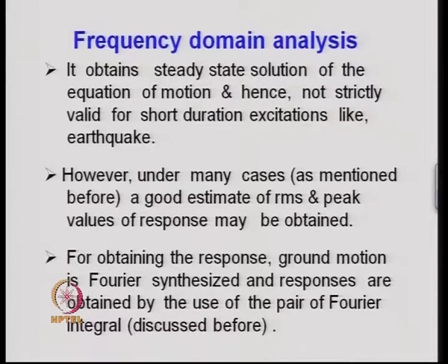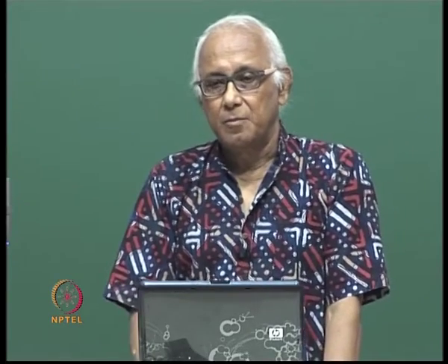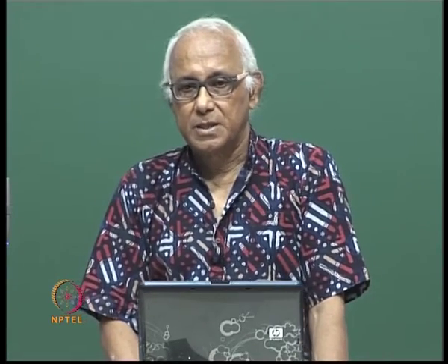However, there are many cases where one can get reasonably good estimate of the root mean square value of the response and the peak value of the response using the frequency domain steady state solution, and that is a condition where the structure's period, if it turns out to be much smaller than the predominant period of excitation, then this frequency domain analysis may reasonably provide a good estimate of the RMS and peak responses.